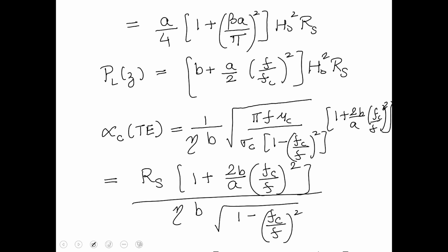That is the loss due to the TE mode. And one thing you would notice is that as B increases, the loss will decrease. Normally you are operating at a much higher value than the cutoff frequency, because at cutoff frequency the loss is going to be very, very large. So you're operating a few times higher than the cutoff frequency. So this term is small. So if I was looking at the geometry, as I increase the value of B, my loss is decreasing.